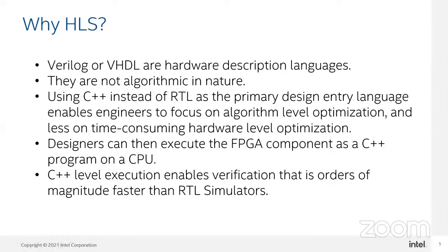And then the designers can execute the FPGA component as a C++ program on a CPU. And the greatest advantage is that C++ level execution enables verification that is orders of magnitude faster than RTL simulators. So we can come to the conclusion that we can enable verification faster than how we do it with RTL.